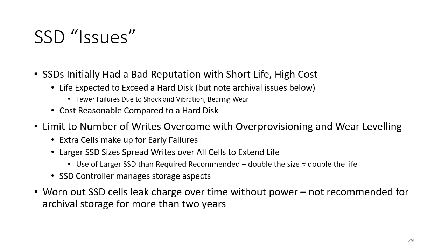But again, if you're buying an expensive industrial PC or a laptop and then not using it for 2 years, you could argue, why did you buy it in the first place? And my experience is I haven't seen this issue of SSD cells leaking charge, probably because I've never had a device that I've not used for more than 2 years. But that is one thing to be aware of. SSDs are not recommended for long-term archival storage if it's not going to be powered up.